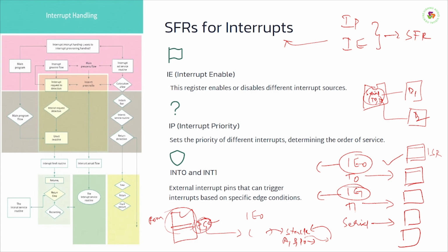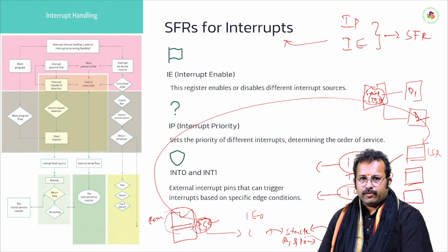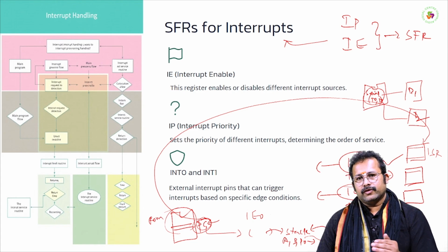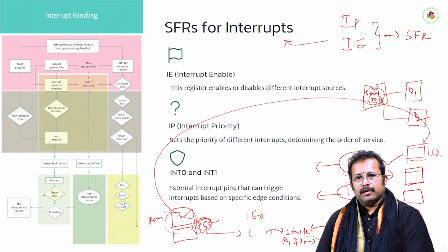The program counter transfers from the main program to execute or acknowledge the interrupt which came. So, whatever interrupt comes during the main program's execution, based on the priority, it will store the data onto the stack and change its course.